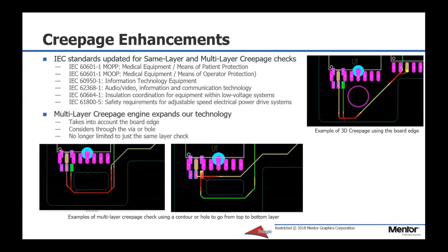So this is where we're saving the customers a maximum amount of time by embedding the charts and standards that they have to follow for their guidelines into the rule. This removes a lot of tediousness of manually checking for creepage. These standards are regulations that companies need to follow depending on the environment that the PCB will be in. So for example, mil-aero or medical device companies with high voltage PCBs have to follow these IEC standards. With these checks, Mentor is the only company on the market providing an automated solution for this layout validation.